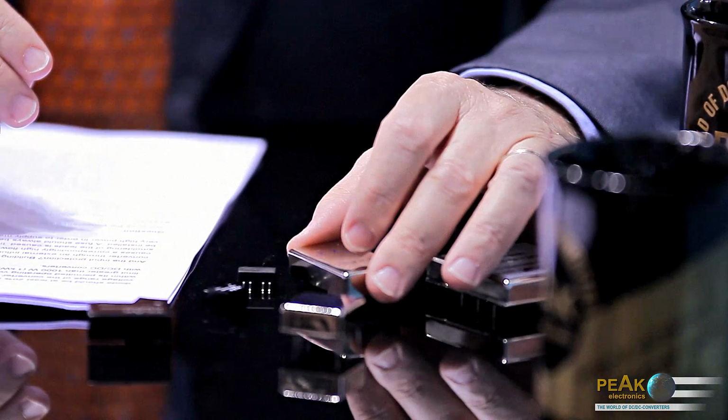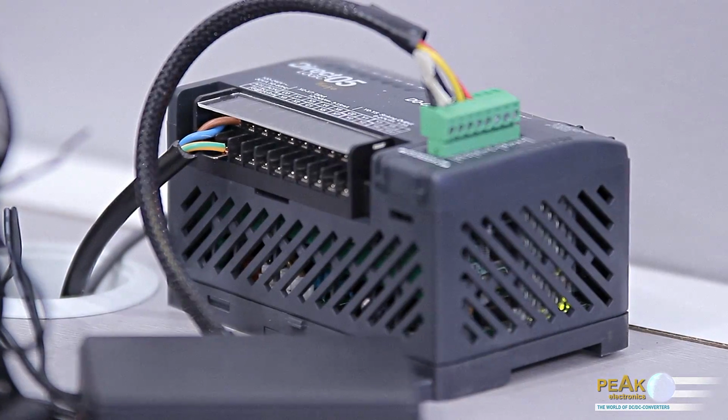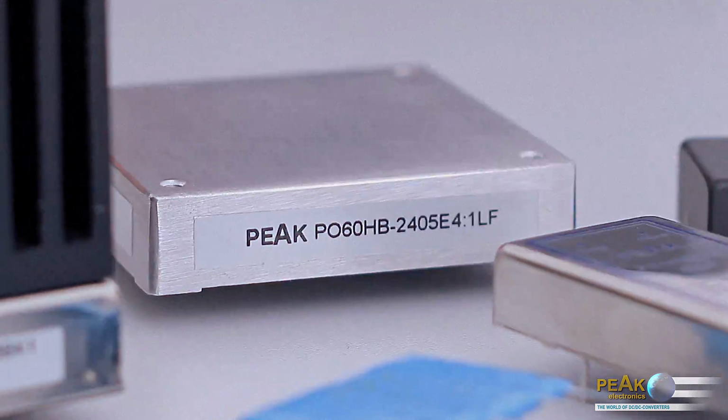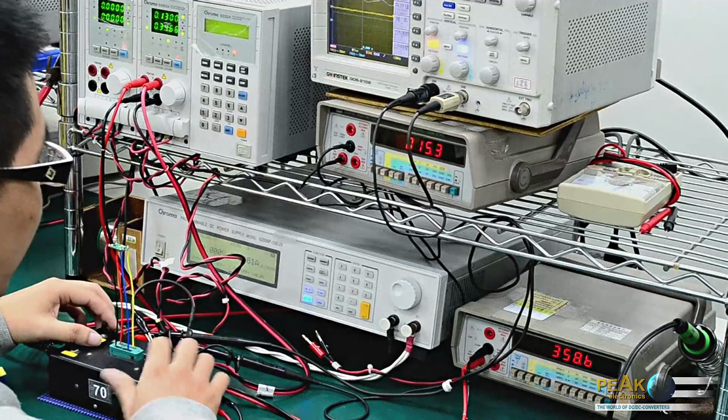In order to correctly dimension the application, also with regard to the thermal situation, some values are important, such as efficiency at a given output power and maximum allowable housing temperature. The power loss and heat dissipation can be calculated from the efficiency and the power. The maximum housing temperature can be simply measured with a temperature measuring instrument under real conditions.